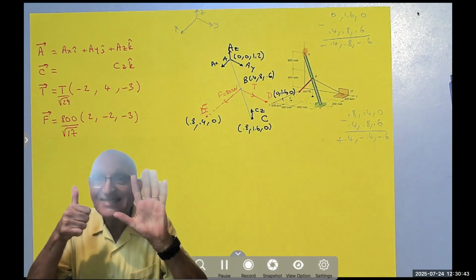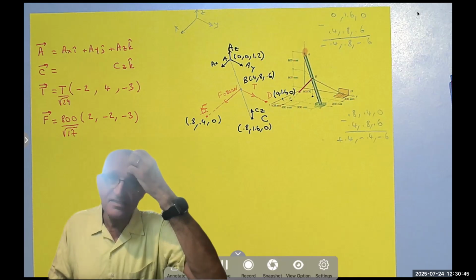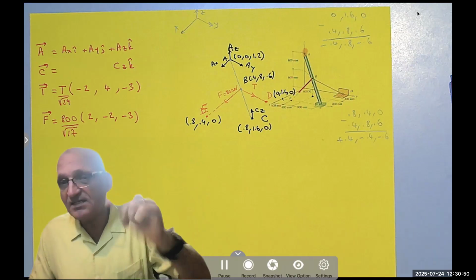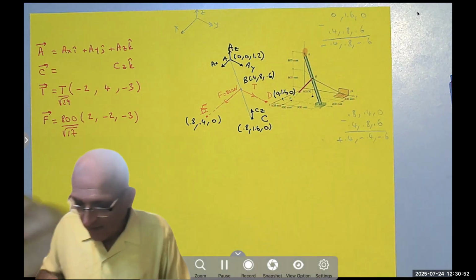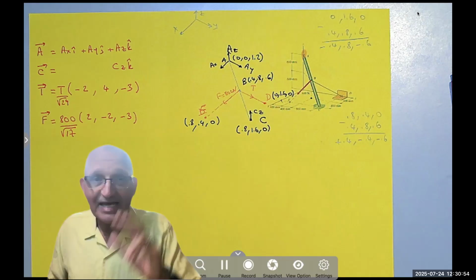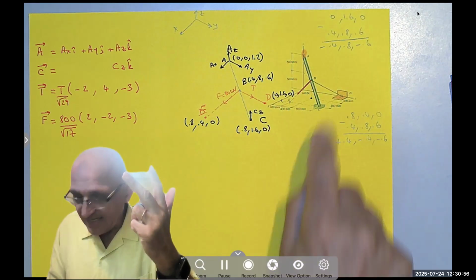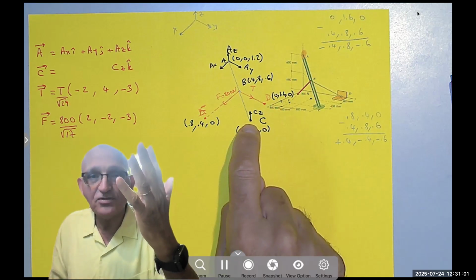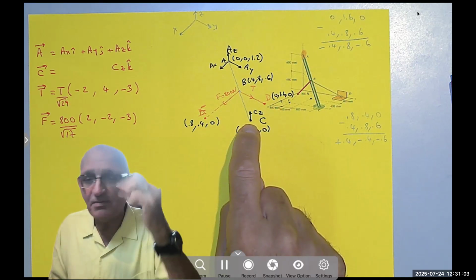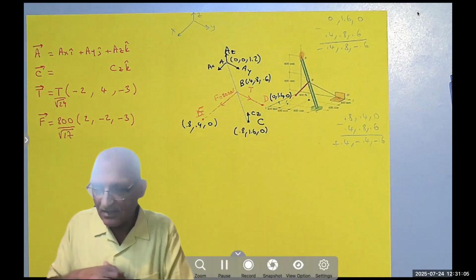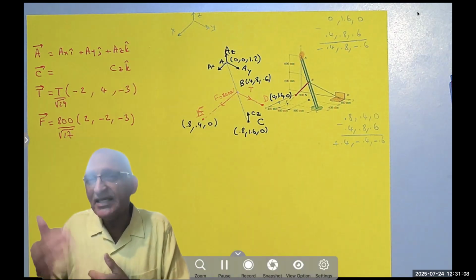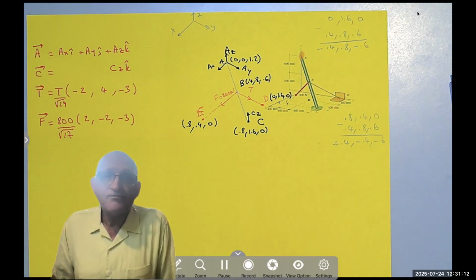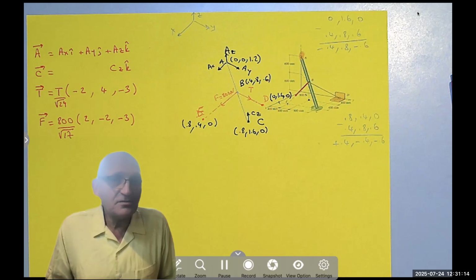I have to write 6 equations in 6 unknowns. Before we continue, and we'll answer this question later, I have 3 unknown reactions for the ball and socket. I have an unknown tension, and I have an unknown Z component of the reaction. That's only 5. Remember, I told you in the previous lecture, in some problems, you may have less than 6, and still this thing is stable.